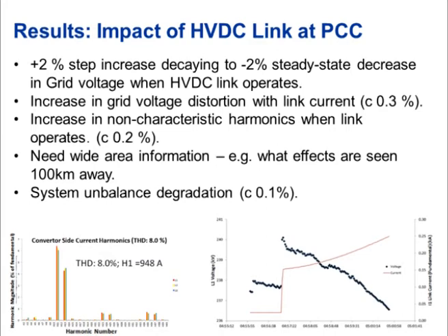These things have got large converters, large thyristor converters, chopping up the DC to turn it into AC with big filter banks, which are major pieces of civil engineering. And one of the things that we want to find out from this study is how to measure the impedance looking into the grid so that filter designers can make a better job of filtering out those harmonics. And that's one of the main things that we're doing on this ongoing study, looking at the impedance of the network as the seasons change and as load and generation is brought on and off. And we were able to see a number of findings there, some change in non-characteristic harmonics.